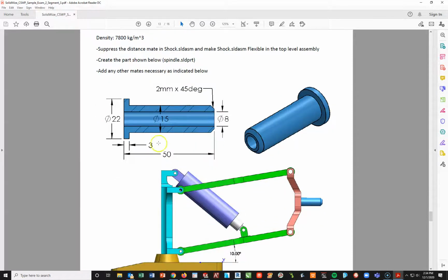In this case, I'm just going to start this from a front view, create this profile you see here in this view, and I'm just going to do a simple revolve. And I'm actually going to go ahead and start by going from the origin with a center line, create this upper part right here, and revolve it around. I'm going to try to do this in one step.